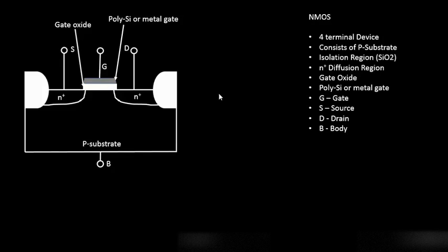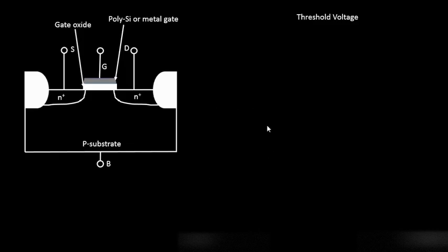Okay, so the most important topic that will drive all your SPICE simulations is the threshold voltage. So why am I emphasizing the term threshold voltage? Because when we do SPICE simulations, the terms which are involved in describing the threshold voltage of an NMOS transistor, those are the models. Those are the ones that will represent your NMOS transistor. So I'll come very soon to how we do that exactly. So for now, we'll just try to understand what is threshold voltage. Next, we'll try to understand the terms involved in the threshold voltage, and how those terms model any transistor.